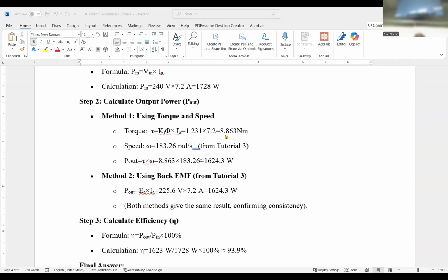Different professors have different presentations, but I use this presentation to show you how the motor works under that particular condition. For more complicated control, we may need to control differently. Anyway, we have a DC motor controlled by a PWM converter with a 200 volt DC source. We're not applying 200 volt to the motor directly, but through a PWM converter. The switching frequency is 10K, armature resistance 0.8.